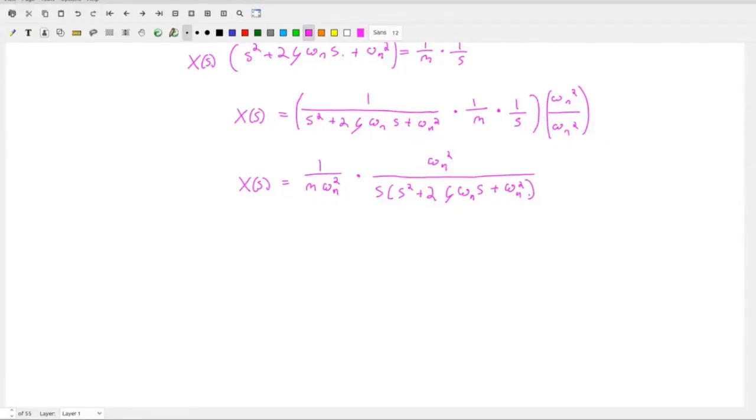So let's go ahead and take the Laplace of this. The component here that leads does not have any s's in it, right? So we can just pull that through. Does that make sense? And then number 11 is going to give us 1 minus omega n over omega d e to the negative zeta omega n t sine of omega d t.